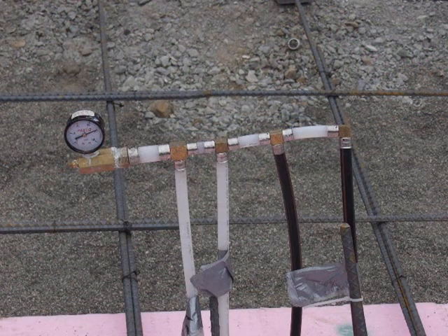Well, the final thing to do before you actually pour your concrete is to test the tubes to make sure there's no leaks anywhere or pinholes in the line. Basically, you want to set about 80 or 90 pounds of air into these lines and let them sit overnight. Come back the next day, look at the gauge, make sure that there's no decrease in pressure. If there's no decrease in pressure, you're all set, you can get going. If there is a decrease in pressure, then you have to do some troubleshooting to find out where that is.